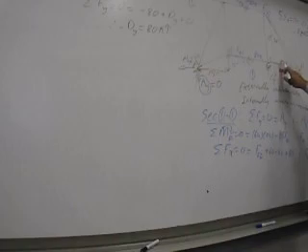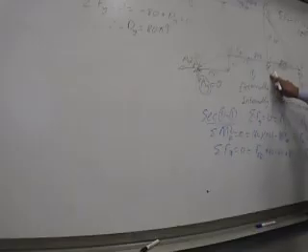Here this guy will be 80 kips, and if you look at this, you see why it came out negative 80 going down. So this will be an 80 tension. Okay, you can solve the remaining members. Okay, are you lost?